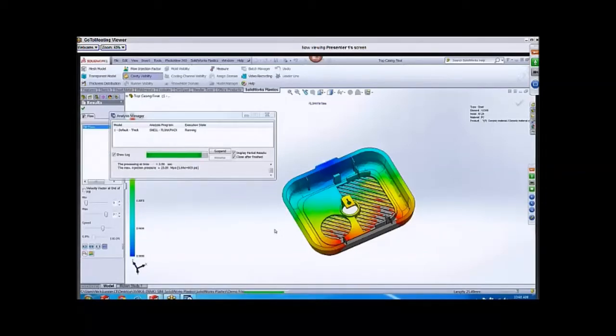So it's not good in that sense, but it's also not good in the sense that the plastic at that location isn't going to be as strong. So if you can possibly eliminate the weld lines from all of those critical locations where it's going to be visible and where it's going to need to hold up to strength, that's ideal.